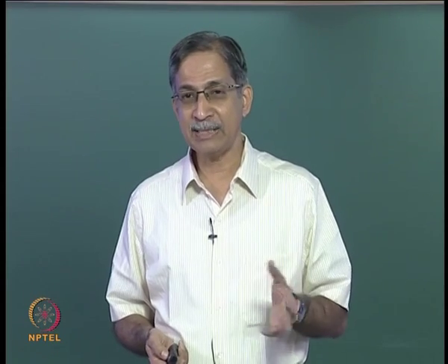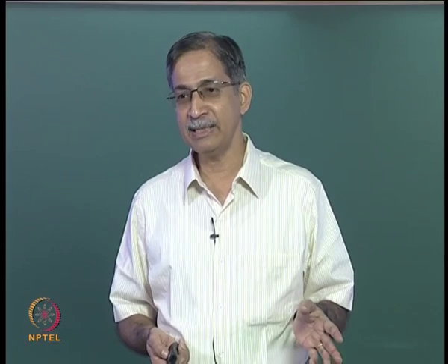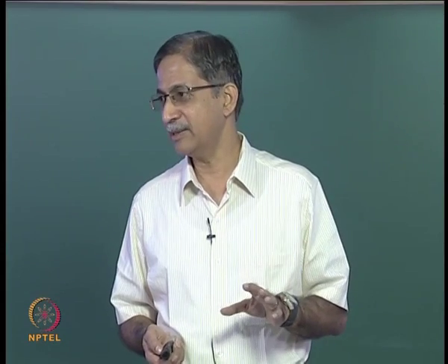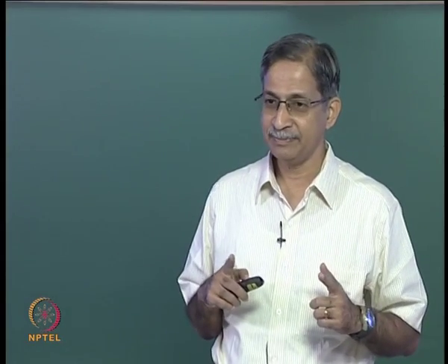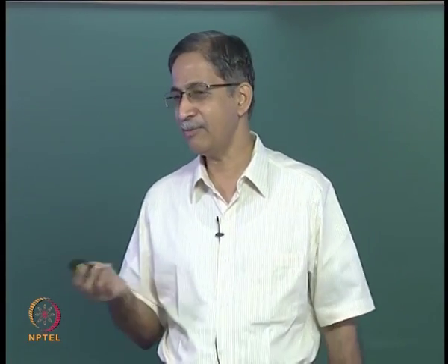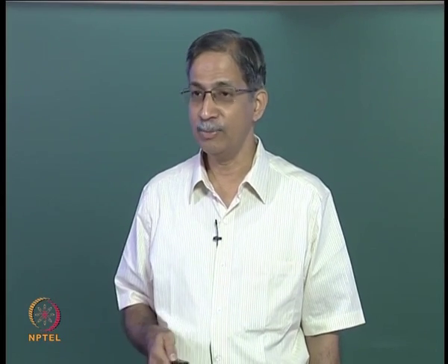We will expect some difference between ignoring axial deformation case and including axial deformation case, and that will be a little more pronounced when you have sloping legs. Okay, we will see that. Apart from that, you should get the same answers we got when we did the slope deflection method.